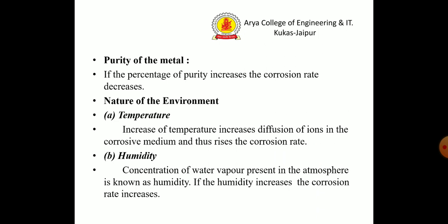An increase of temperature increases the diffusion of ions in the corrosion medium, and it increases the corrosion rate. And the second factor is humidity. The concentration of water vapor present in the atmosphere is known as humidity. If the humidity increases, the corrosion rate will increase.